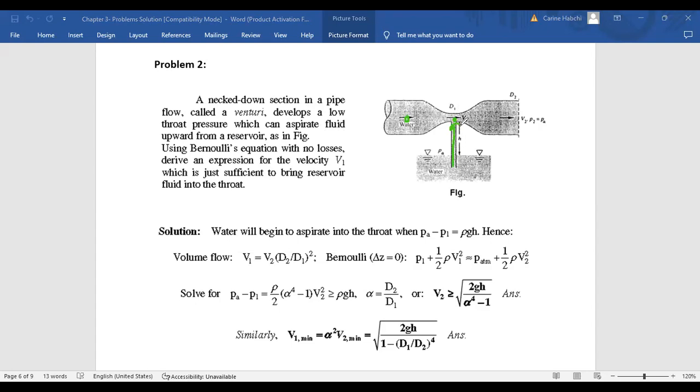Because this will help. Here you have a pressure, let's say P atmospheric, okay? If you impose a pressure at this level larger than the pressure here, this will lead to fluid motion upward. Why does the fluid rise? Because you are creating a pressure drop between the level of water and this level here, okay.